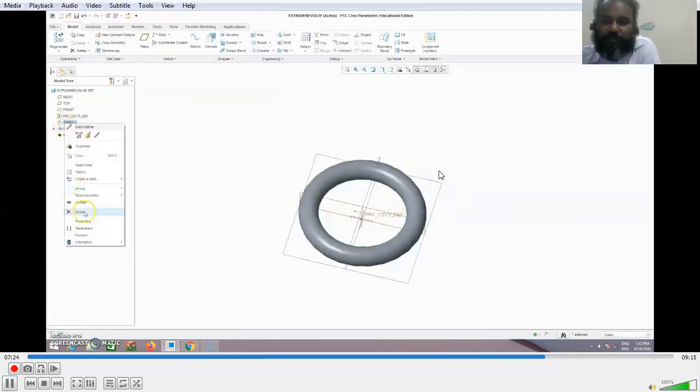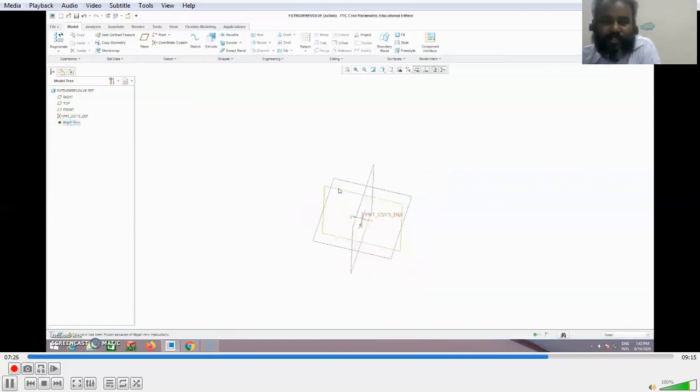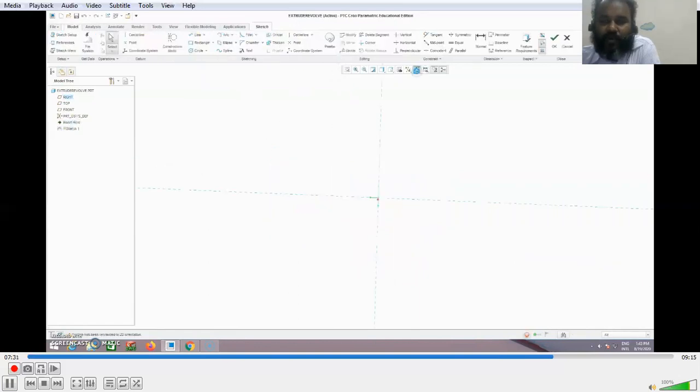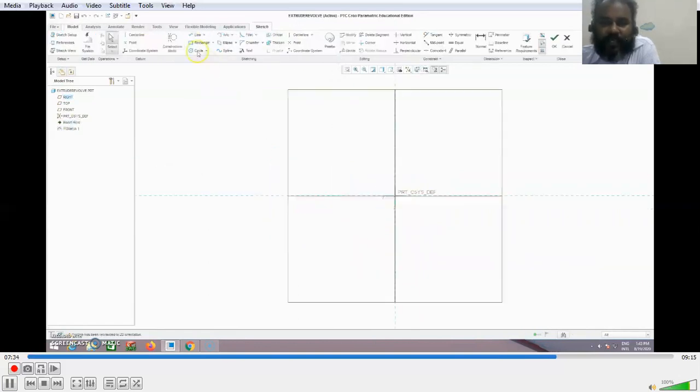So this is simple. You can try out all the other things that you wish to create. And finally, we want to show you one more feature of revolve. So I'm making a circle at the center of the plane. If I revolve with this as the center line, what do I get? That you can try on your own, that would be an exercise that you could do. What I'm going to do is, instead of having this entire circle, I'm going to remove this segment of the arc and this segment of the arc, and rotate only the semicircle with this as the center line.